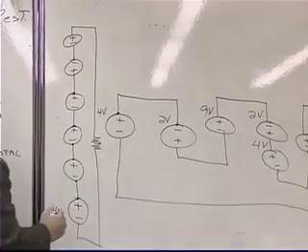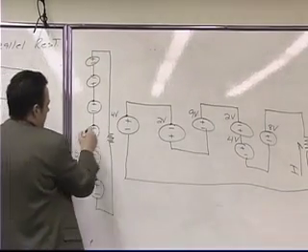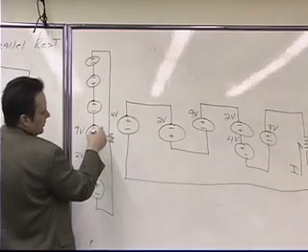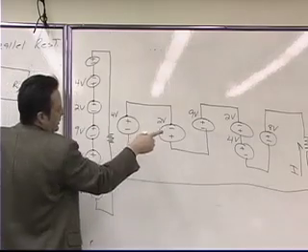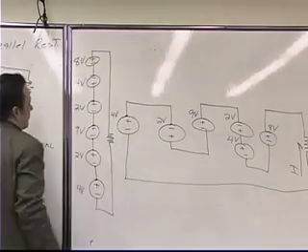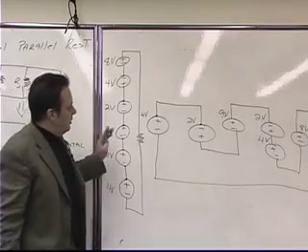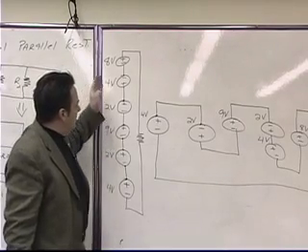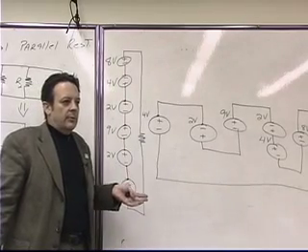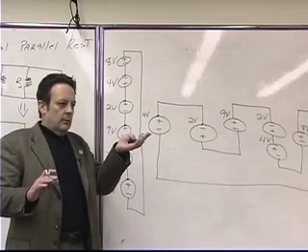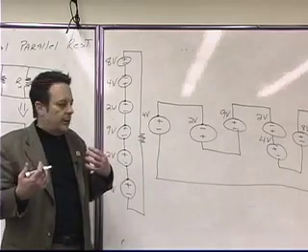Okay? So now I can draw my polarities. So I've got 4 volts, I've got 2 volts, I've got 9 volts, I've got 2 volts, I've got 4 volts, and then finally I've got 8 volts. Okay, now, one of the things that makes it a lot simpler when it's all drawn vertically like this is I can figure out which batteries are aiding to the electrical pressure and which ones are taking away from the electrical pressure.